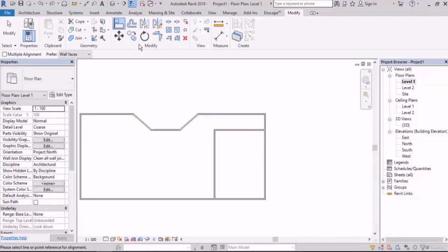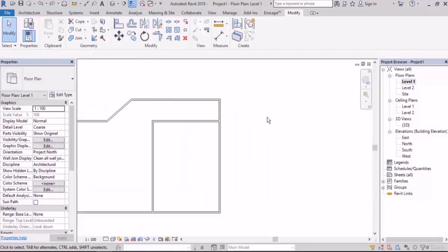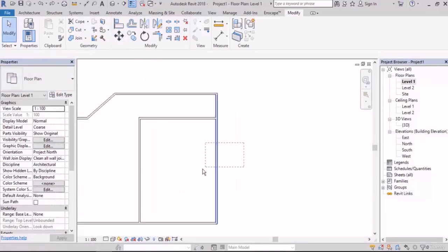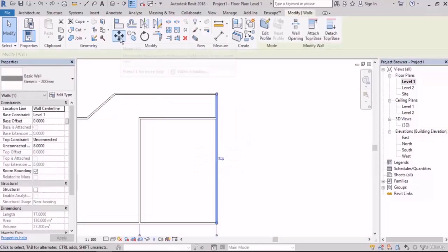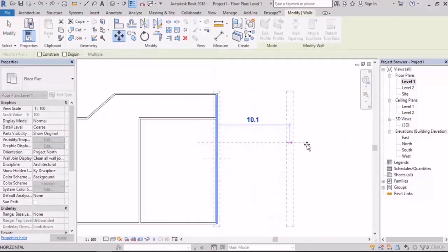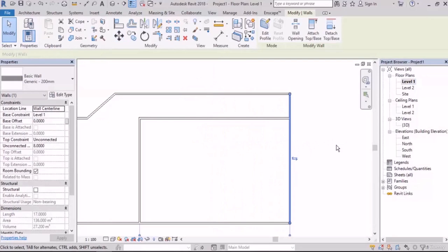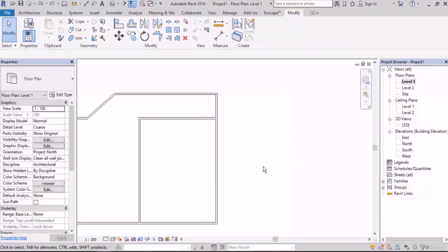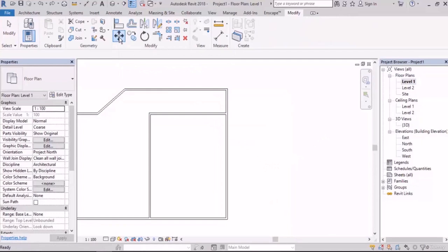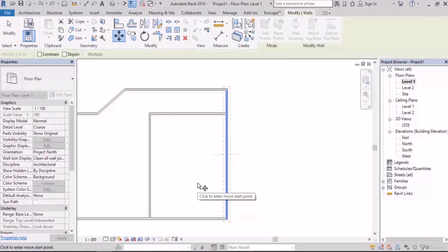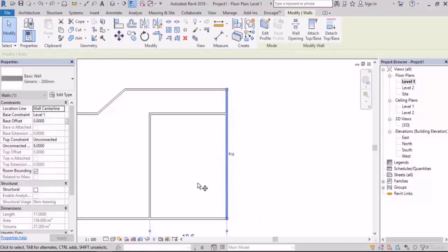We don't select. The tools that need a select, like move, one way is to select the object first and then click on move, and another way is that first click on move and then select the part, and I've seen a lot of people do it. Well, it's okay, but you need to click on enter after that too so that it works, because it must know that your select is over.